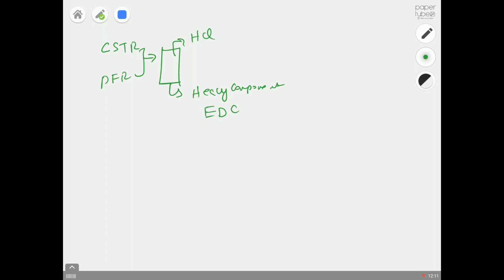This will be roughly 60% purity, but we can check this later using Aspen HYSYS. And then we further purify it using a liquid extractor, using water as the extractant.